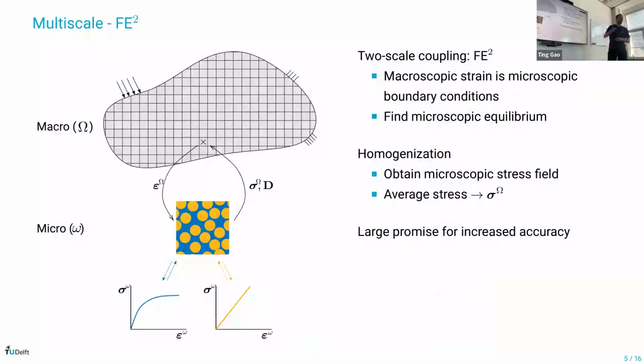But to get a more accurate simulation, we need to go to what we call a multi-scale approach, where in every integration point of your finite element method, we embed another finite element method to get the properties from. So here we have two different materials at the lower scale, which we can define very well on their own. But again, combined, it really depends on the orientation of the fibers or the layout what the actual response will be. And so solving a single scale is still quite fast, but doing this for every integration point, solving another system, becomes really, really expensive.